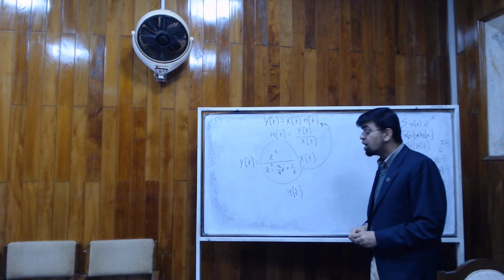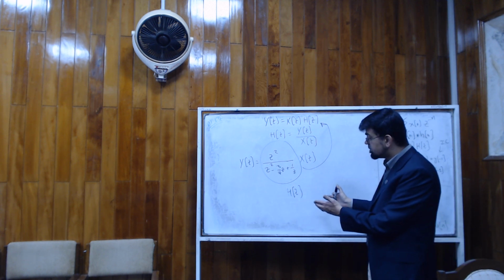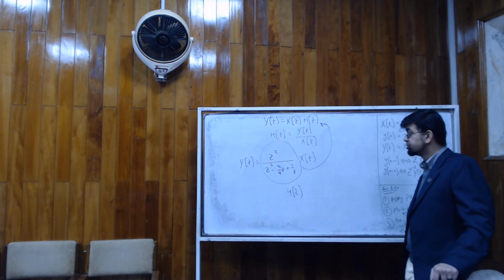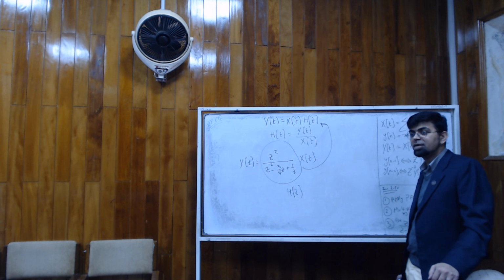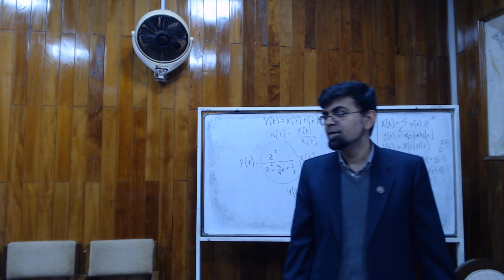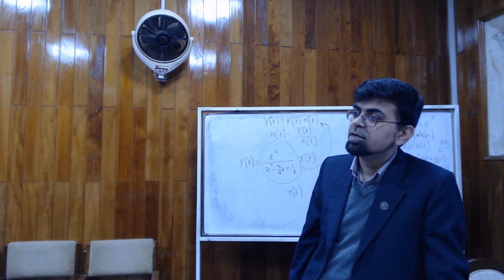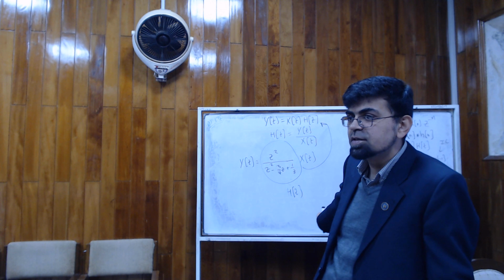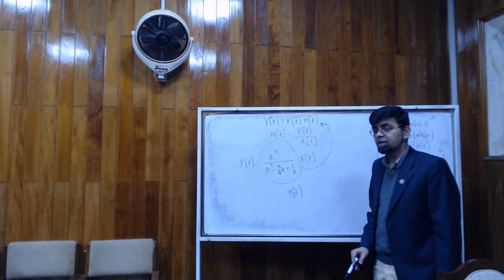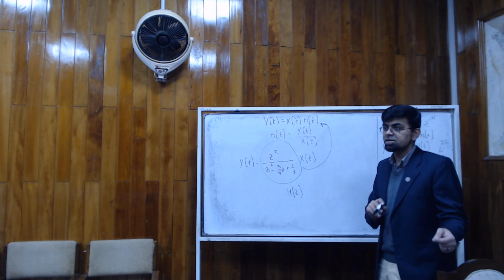Now, follow-up question, last one, based on this. Is this system stable? Yes, sir. Okay, why? Good question. Good question. How do you check stability in frequency domain? Check the poles of the transfer function. Remember? हमने किया था ये last time भी. Check the poles of the transfer function. For discrete time systems, the poles have to be inside the unit circle.